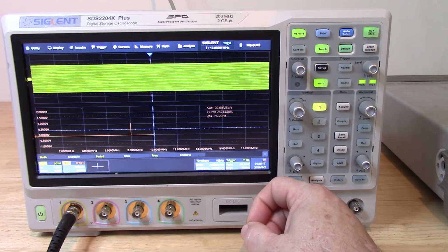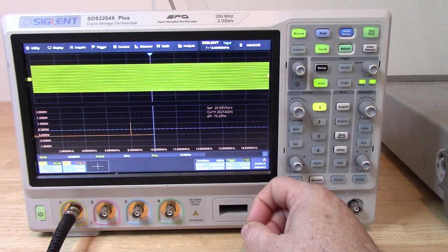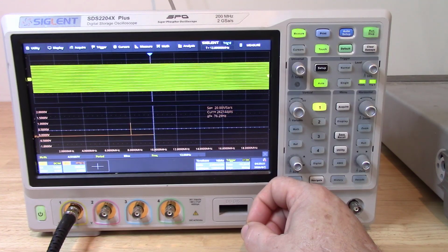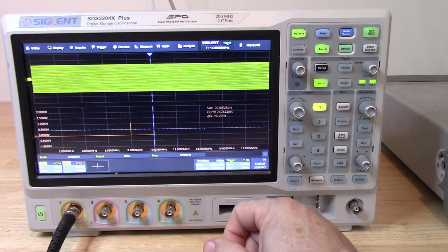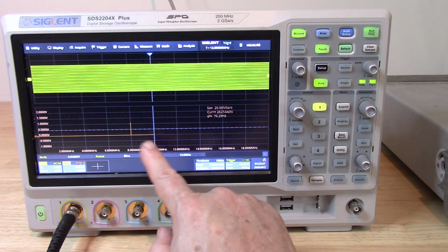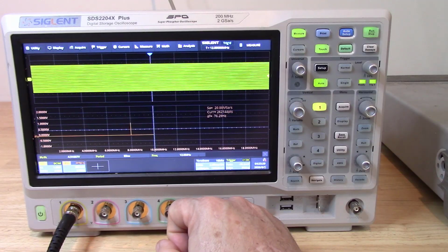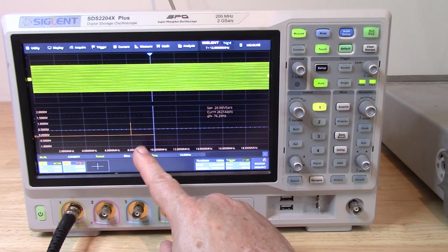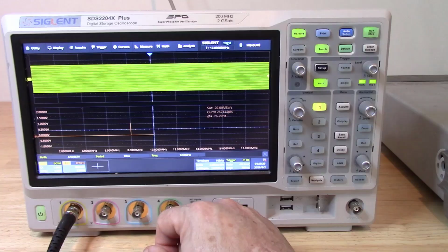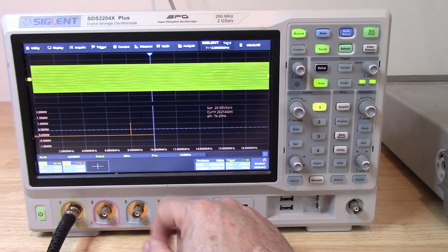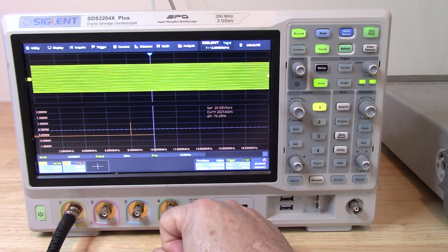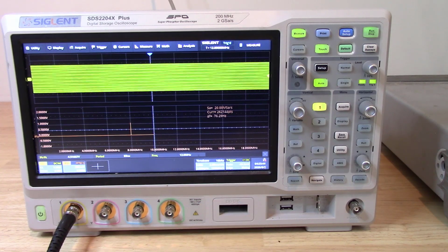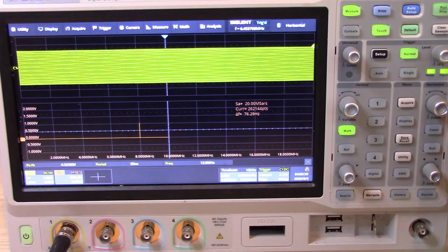Aliasing is an artifact of sampling and totally contingent upon sampling frequency. So your sampling frequency is going to be important, your Nyquist frequency is going to be important, your signal frequency is going to be important, because you need to know the difference between your signal frequency and the Nyquist frequency to be able to predict where the alias sine wave will occur in frequency.